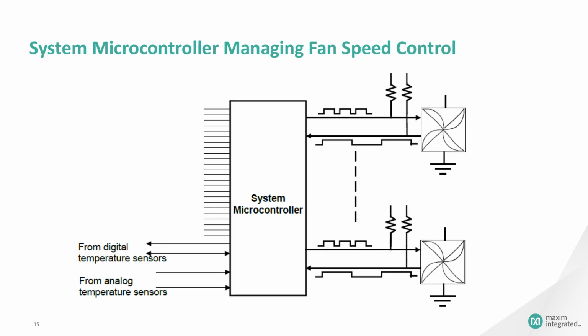If the system design already includes a microcontroller performing system management tasks, that microcontroller may also be able to handle fan speed control functions. The microcontroller needs to have enough IOs available to monitor tach signals and generate PWM speed control signals.